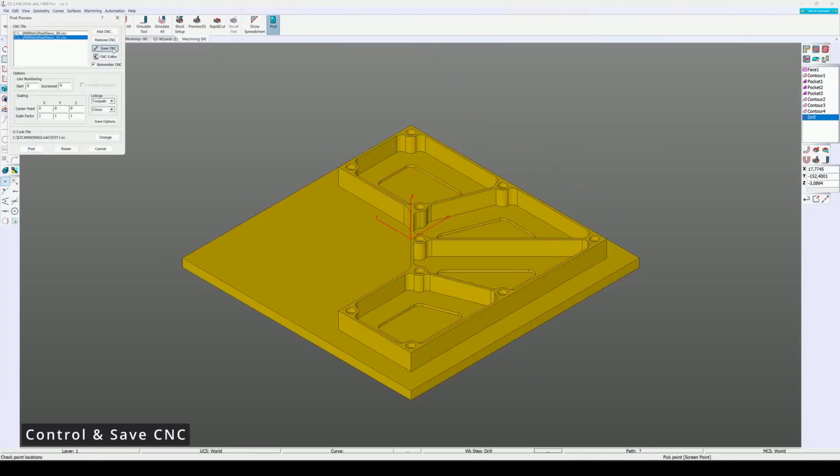If everything looks correct, save the postprocessor permanently using Save CNC. If you skip this step and close the program, the in-memory changes will be erased. Note this. Each time we click Save and Import from the Assistant, the Save CNC button in EZCAM becomes active. If there are no new changes, the button stays inactive.